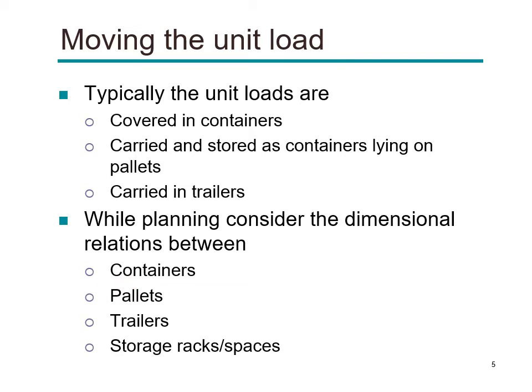The pallet sizes, usually they are standard. There are different standards. And in order to design your unit load and your containers, for example, you need to design your containers such that a number of containers can fit perfectly on the pallets. Similarly, these pallets should be able to fit on the storage racks perfectly. So the dimensions and the sizes of these storage racks and spaces should be suitable for the containers and pallets and so on. So the dimensional relations are important.